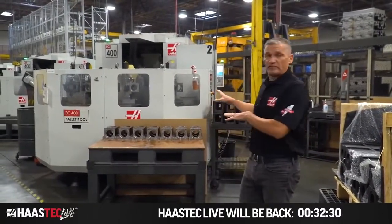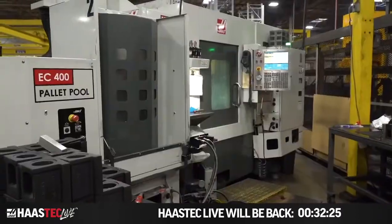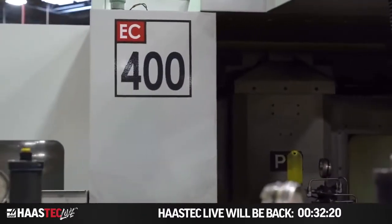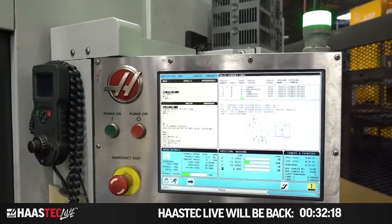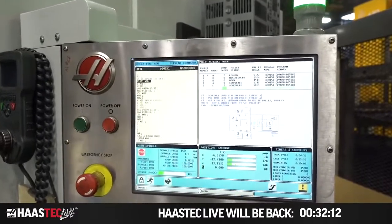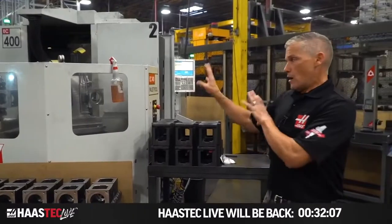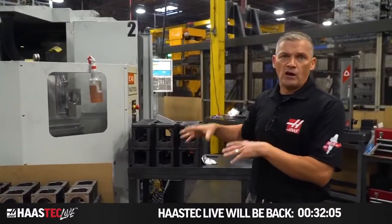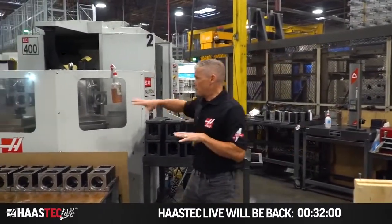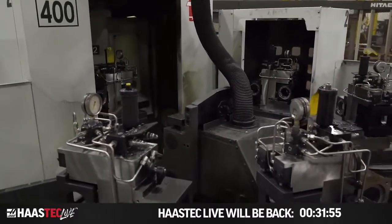Now, this is kind of an example, well, this is completely an example of how HaasTech does the same style of machine as those FMS systems we just looked at. But in this case, it's geared towards a medium-sized shop at a much more affordable price level. But the idea here is that these horizontals are aimed at getting a high mixture of parts, or maybe you're focused on one specific part. All of these cells mostly concentrate on 1 or 2 parts or a few parts where we're doing very high volumes. But you can see, when you attach a pallet pool like this to one of these HMCs, you've got a lot of fixture positions.